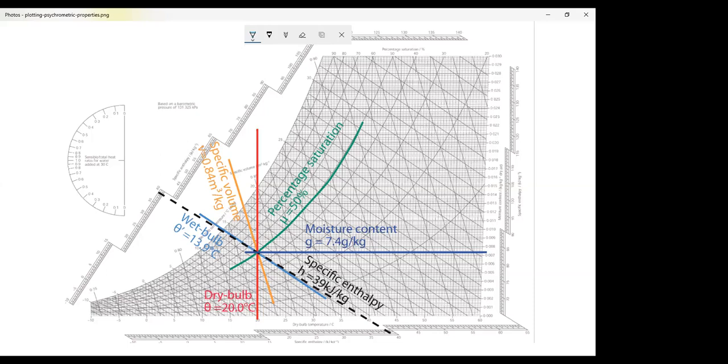Here in this chart we have both wet bulb and enthalpy. In this case, we draw only the wet bulb on the chart, and the enthalpy is represented by another thing. First, start with wet bulb. I need to be sure whether this is wet bulb or not. We do the same check. Here is the curved line for 100% relative humidity, and I check the wet bulb temperature on this inclined line: 5, this 5 here, you see?